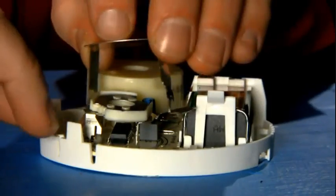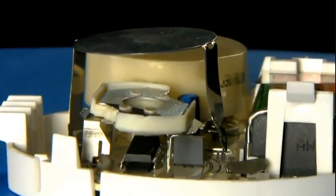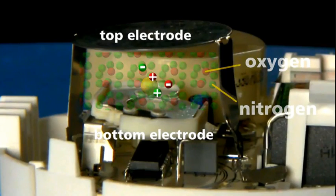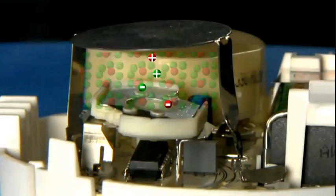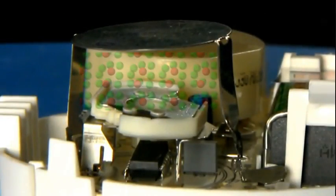Let me explain how. Air flows between these 2 electrodes. Now, of course, air doesn't conduct electricity, but when alpha particles from the radioactive americium slam into the oxygen and nitrogen molecules that make up air, they knock electrons about, leaving charged gas molecules. The 9-volt battery causes these ions to move, thus creating a current. Now, here it's tiny, something like 100 picoamps, about 100 billionth the current flowing in your home. When smoke enters the chamber, the ions attach to it and slow down and often lose their charge. Both events cause the current to stop, which triggers the alarm.